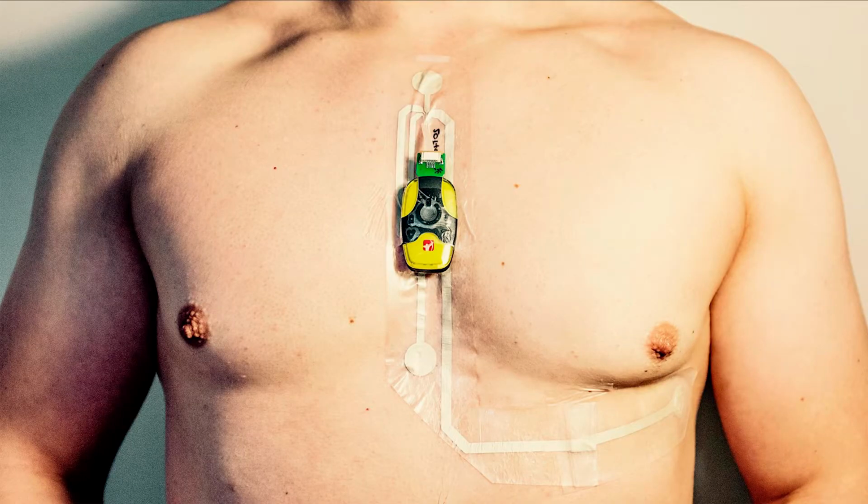To improve the wearability of this type of device, we have developed this printed electrode band-aid for 3-channel ECG and respiration monitoring. This band-aid has been fabricated using screen-printed stretchable silver ink with a stretchable polyurethane substrate.